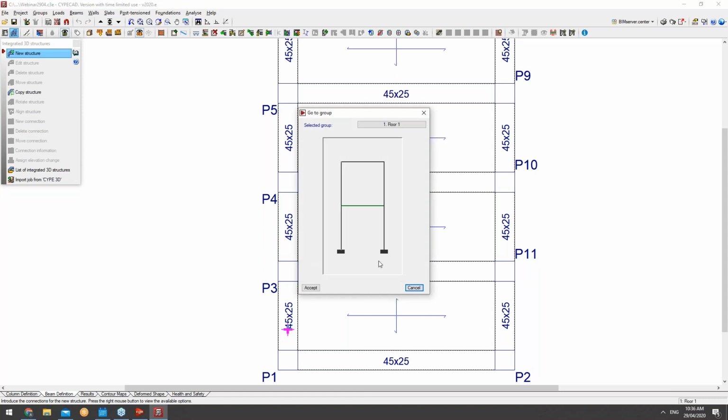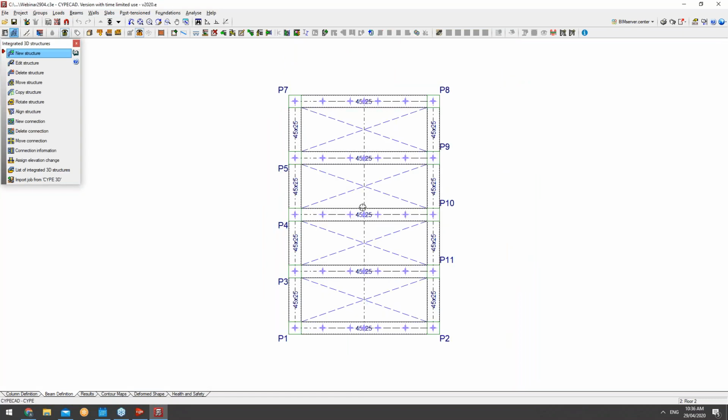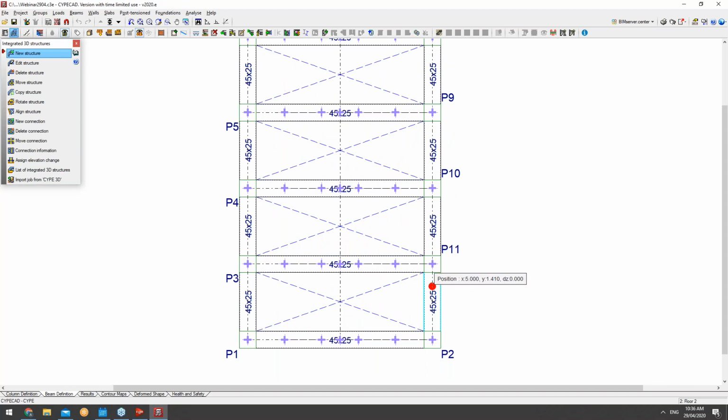Let's change group. Let's go up to the top level. I'm going to now select a different position on the opposite side of the structure. Now, this is just for demonstration purposes, nothing that I'm trying to actually get across. I can now right-click and validate the connections. Now the program knows that I've introduced two connections on my RCC structure, and I've validated them. So these are 2 points that I want to connect by some way in a 3D steel structure.